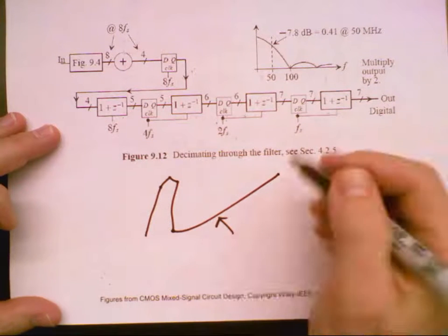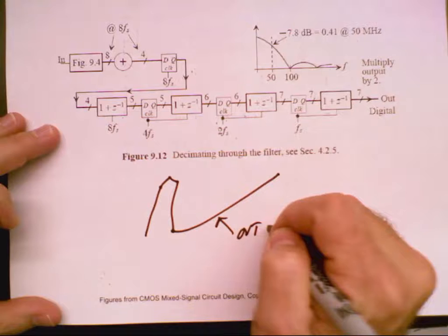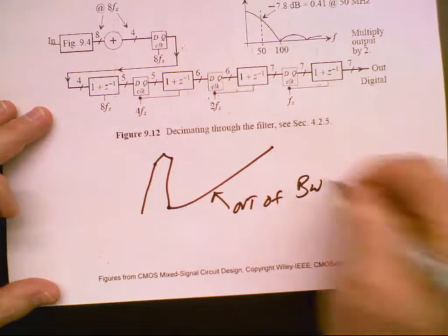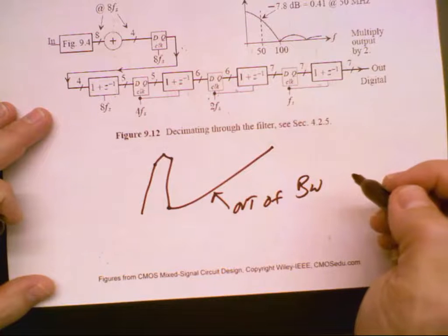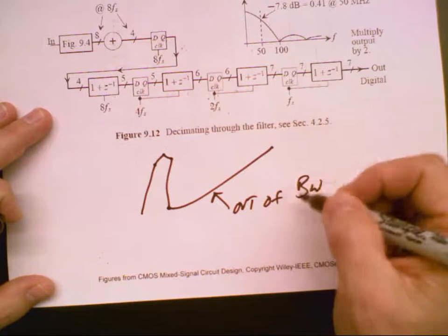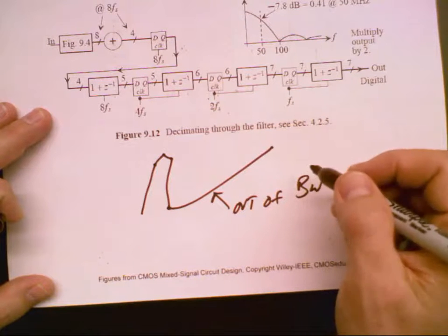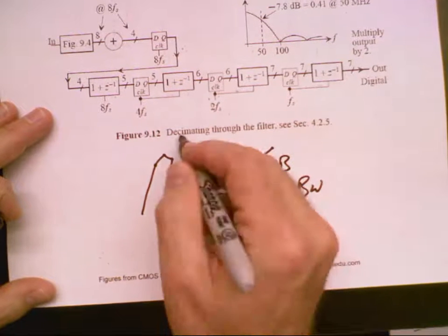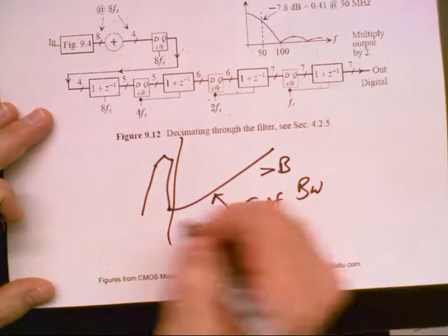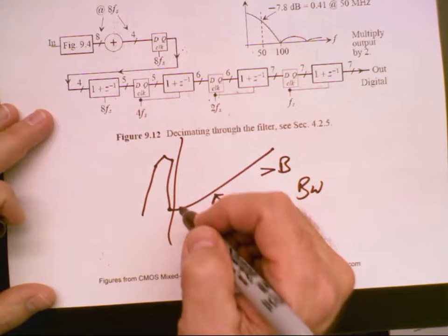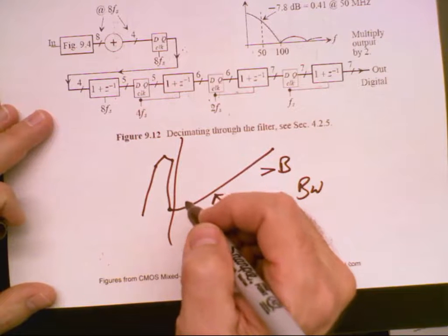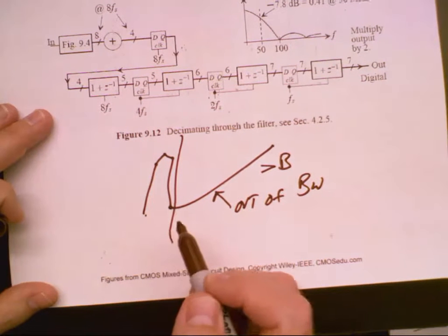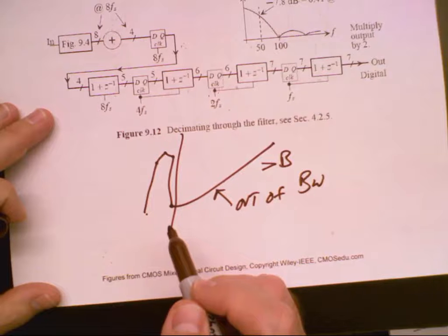So this is out of the band or whatever. What is the proper term? Out of bandwidth. No, I mean, what was the label in the plots? Oh, greater than B. So if you do that and you run a short simulation, your signal to noise ratio is going to shoot up artificially high, right? All you're going to see is green and then nothing, and there's no noise in the spectrum where you're calculating SNR. Okay, that's not good.